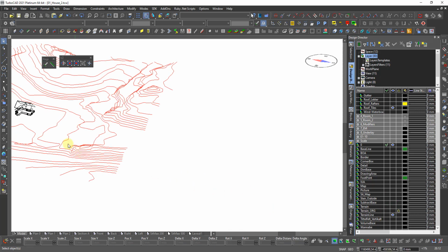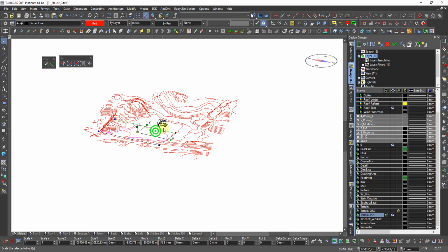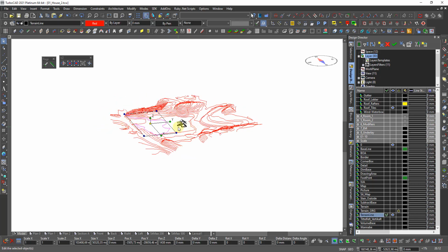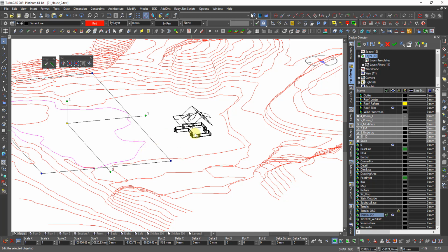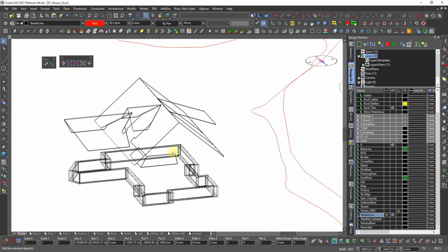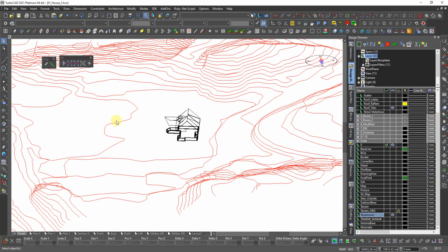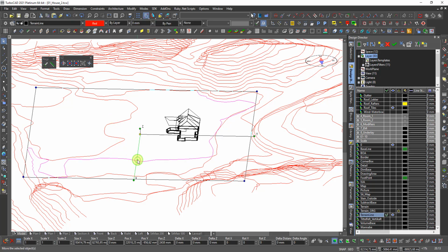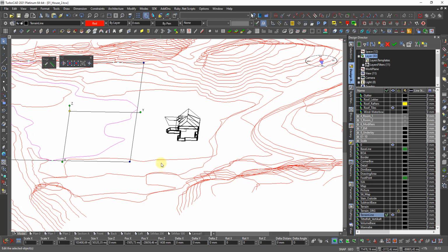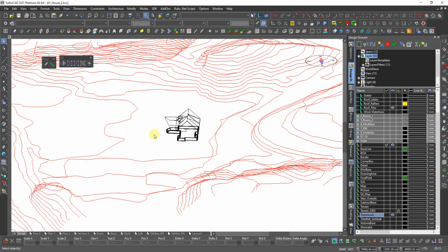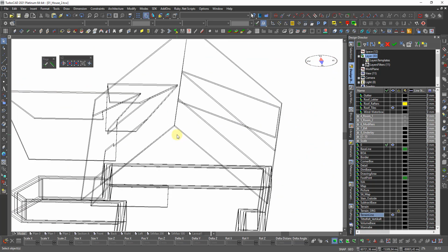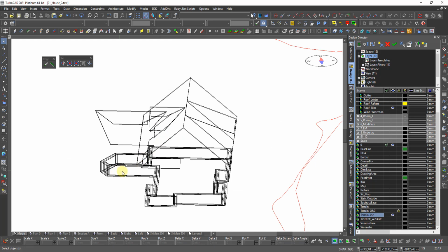And I want to find the line that should be at 16 meters, that is this one. And I want to take the measurement from this to this, just to be sure that we are on the same level. This is the 16 meter, this is the 17 meter. Now it's 2438. That's 1438. So this one, and then I can say work plane by face.